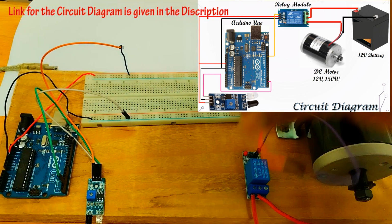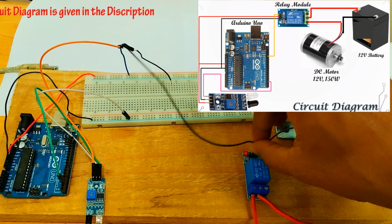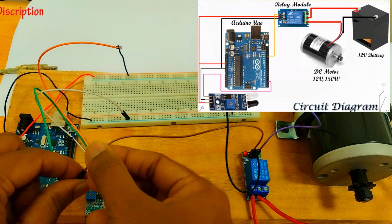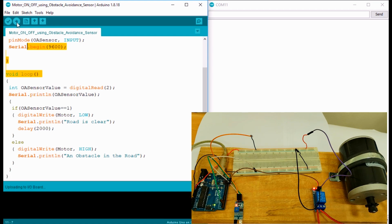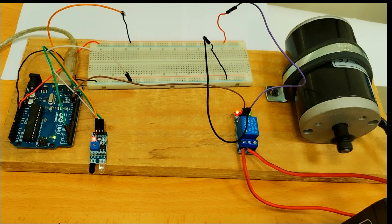Connect the VCC of the relay module to the VCC line of the breadboard. Connect the ground pin of the relay module to the ground line of the breadboard. Connect the input of the relay module to pin number 13 of the Arduino Uno board. Go to tools, select the board correctly, select the COM port correctly, and click the upload button. The code is uploaded. Now you can see in the serial monitor that there is no obstacle.